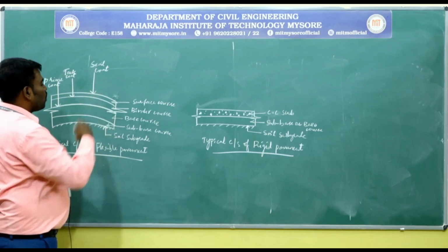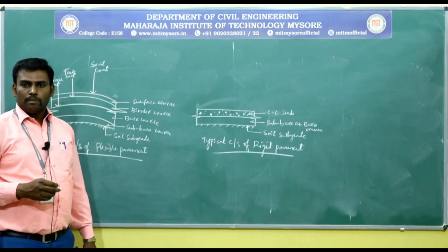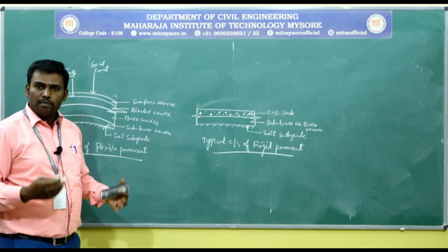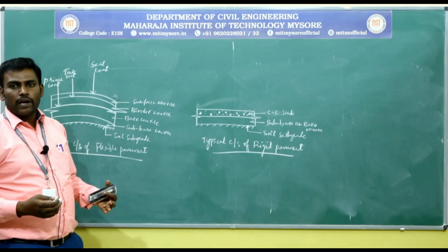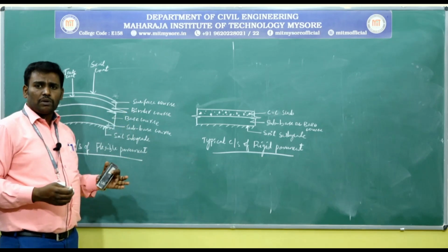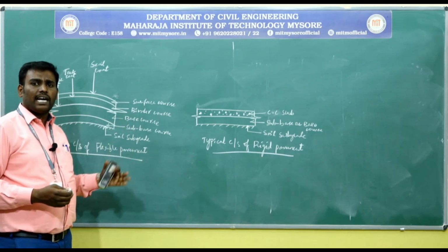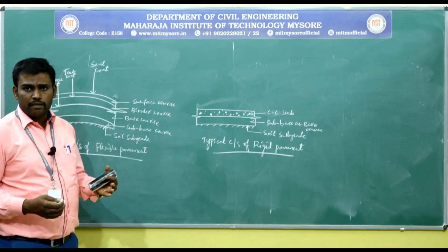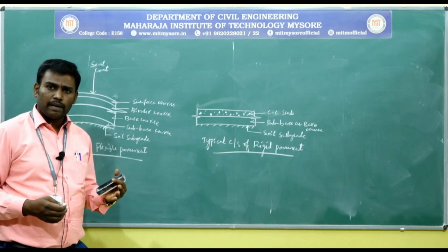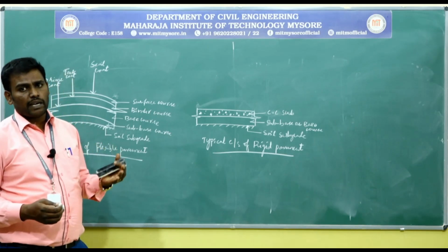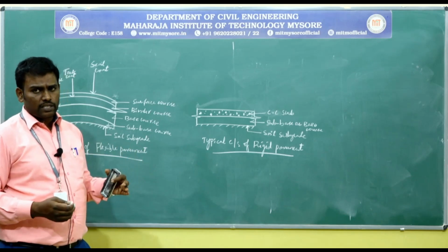Above the base course, there is a binder course. The binder course is also a bituminous mix layer only. Usually we are going to provide a bituminous mix like BM, that is bituminous macadam, SDBM, semi-dense bituminous macadam, or DBM, dense bituminous macadam as binder course layers.